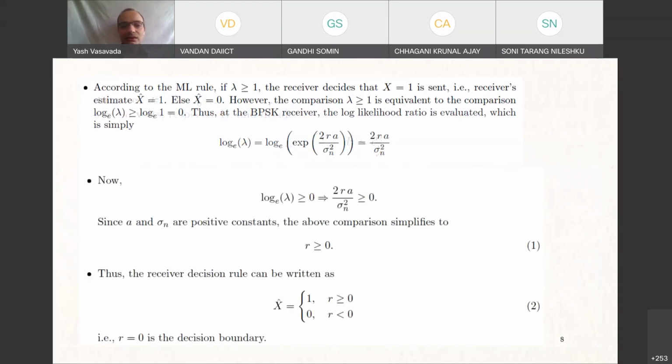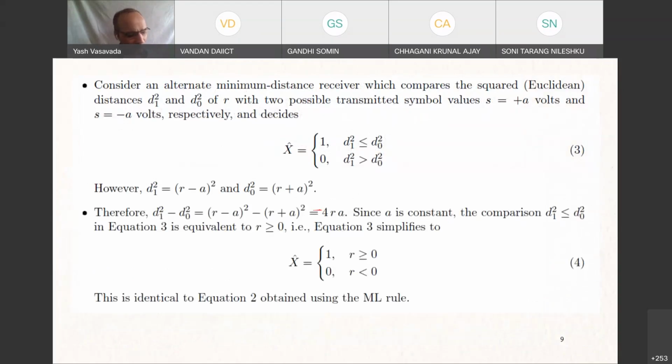Coming back to the theory and taking this more seriously. Although the minimum distance decoder and the Bayesian decoder become identical only for the Gaussian noise channel and only when the priors are equal, even then this minimum distance decoding finds a lot of application in the machine learning community, in communication theory, in estimation and detection theory, in learning algorithms, etc. And actually, we have already seen one such technique earlier. Who can tell me that? Where we were applying the same idea of minimizing the distance. Yes, the Hamming decoder. Correct.